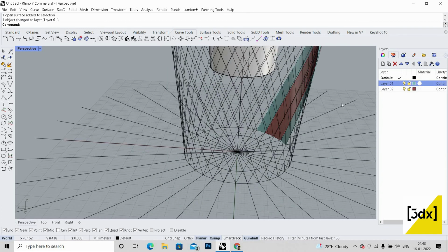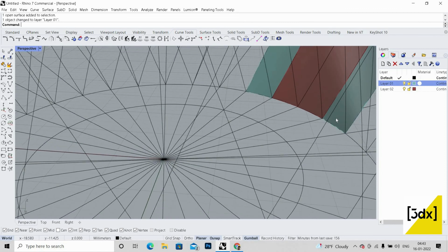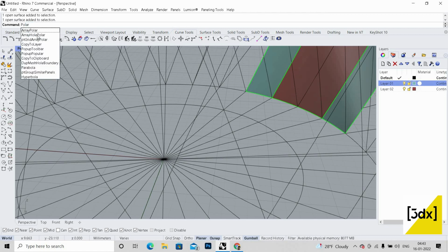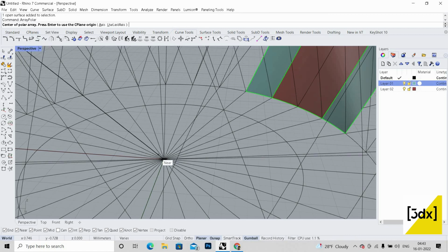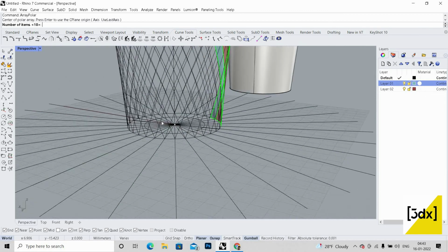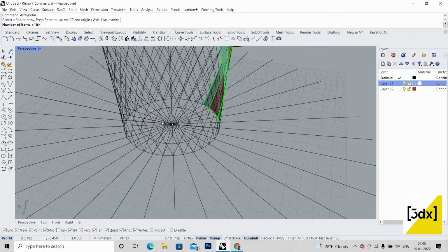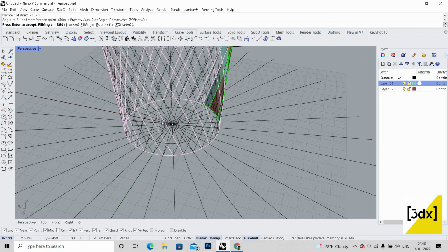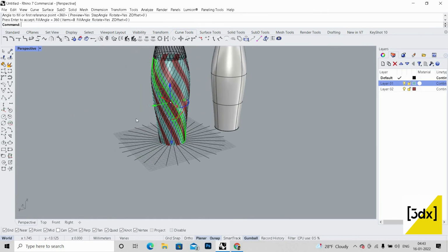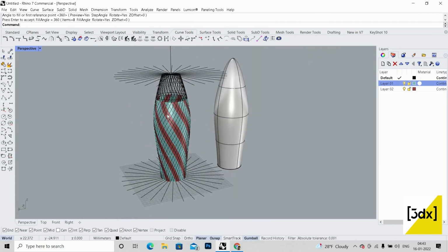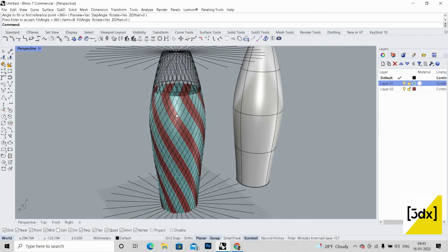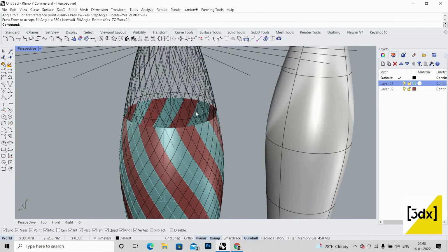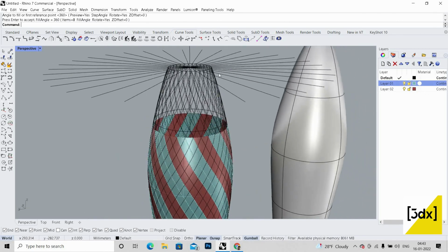Now I'm going to select the line and use polar array. Maybe, yeah, it's around 32. So 32 by 4, that's 8, so I can give a number of 8. So it's been created. So I used this polar array option to create this part.